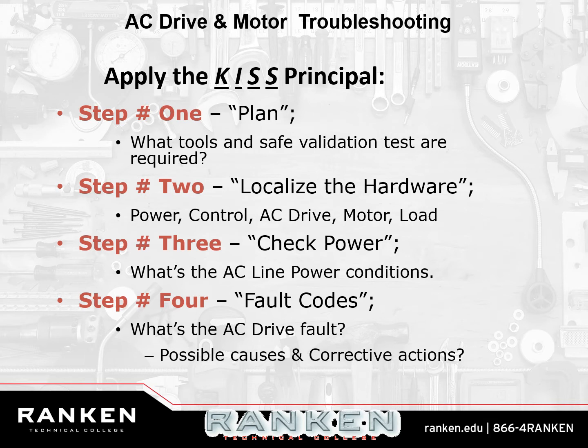The next thing, we check power. Make sure all the AC line power conditions are met. We want balanced 3-phase. We want the correct amount of voltage within a couple of percentage points, and we want as clean and as non-harmonic power conditions as we can get. After you've checked that, check the fault codes on the front of the drive. And without having actually been in the shop to actually touch a drive, this is going to be a little bit more difficult than you think.